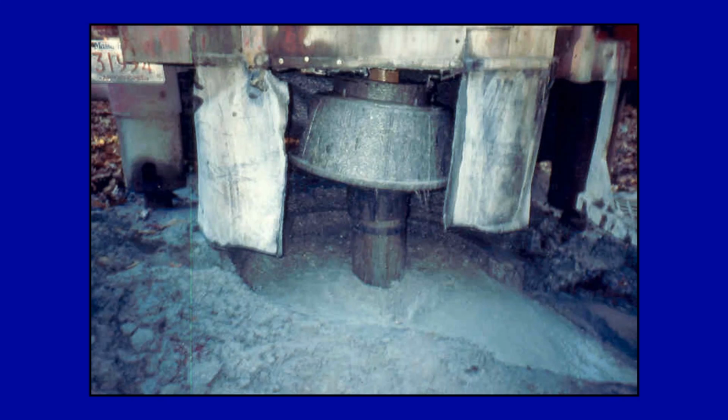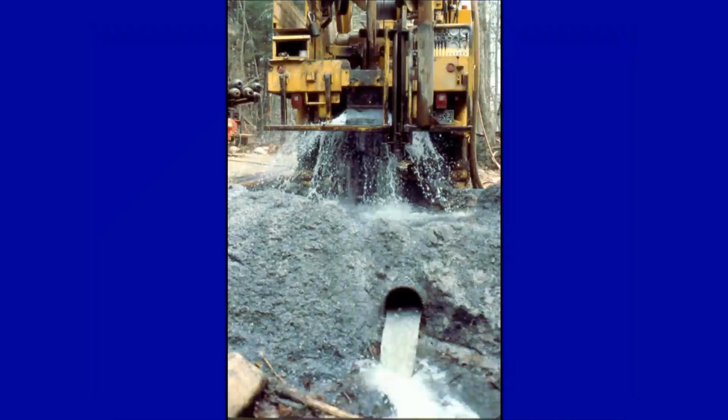If it then turns out that the yield may be potentially greater, you have the opportunity to ream the well out to the diameter of the steel casing. And the way that you get a preliminary idea of what the yield is, because you are pumping with compressed air, is to set a pipe of a certain diameter inside a small dam, and from the invert to the elevation of the water will give you a preliminary gallons per minute.